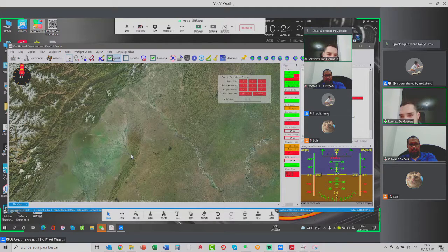Repeat, please. I mean we have the local flight plan and the remote flight plan, right? The local flight plan means the flight plan is only generated on the software, not yet sent to the autopilot. The color is white, and you can edit the local flight plan waypoint or the whole waypoint set. You got my point?